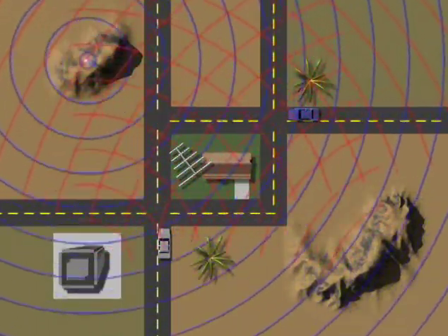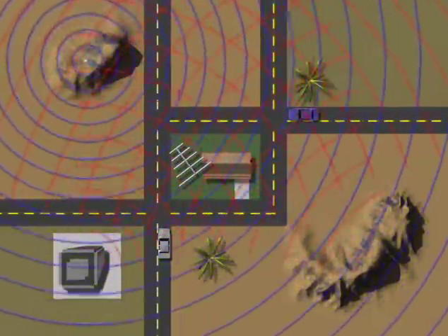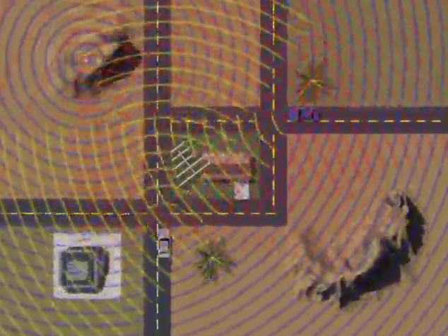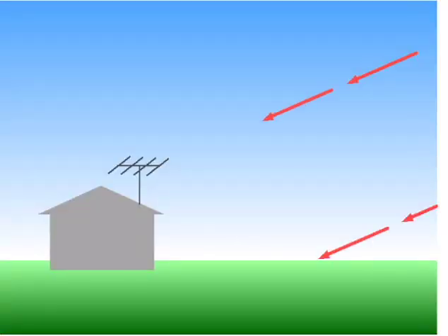Multipath signals can be a problem at VHF frequencies, but the effect gets worse as the frequency increases, since smaller and smaller objects become more reflective. At high UHF frequencies, it becomes a major problem. Multipath signals can also occur from ground reflections from the transmitter to the receiving antenna. Now, depending on the path difference of the reflected signal, it can either attenuate or enhance the signal by as much as 6 dB. Therefore, it's a good idea to test the antenna at different heights for best signal if possible. Moving the antenna up or down a few feet can make a big difference.